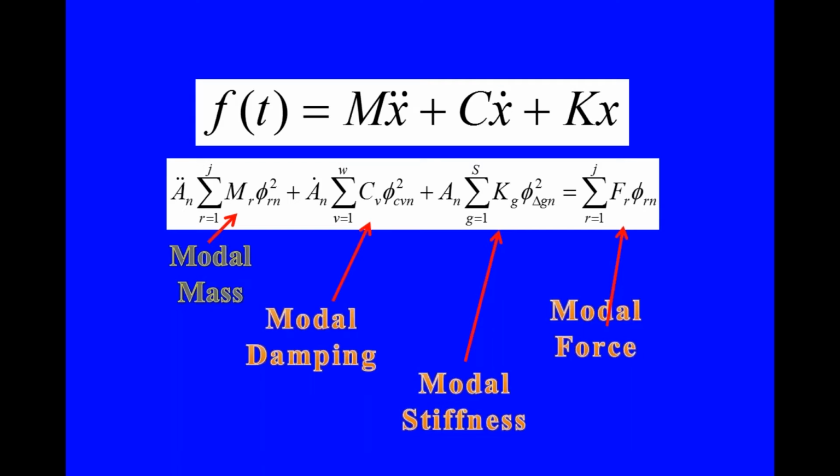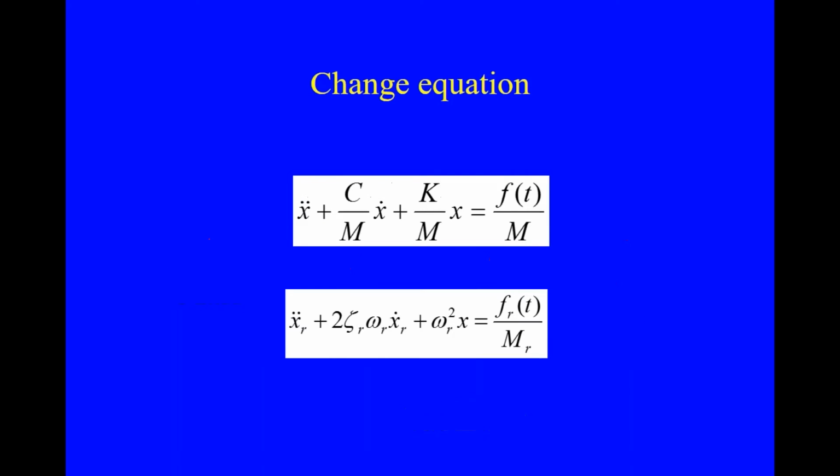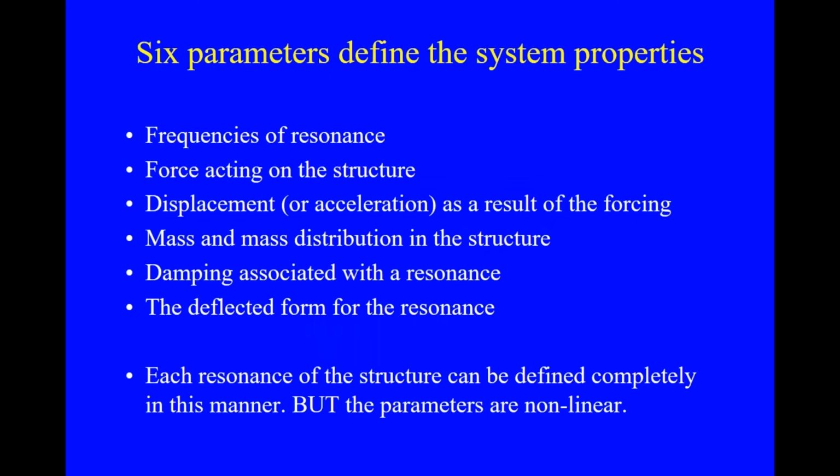Now, I'm not going to belabor this point, but these equations of dynamics actually take us into a lot of detail that we can work with. We can play tunes on this. For a single mode of vibration, what we've actually got is a modal mass and an acceleration. We've got a modal damping, now equivalent viscous damping, and we've got velocity in there.